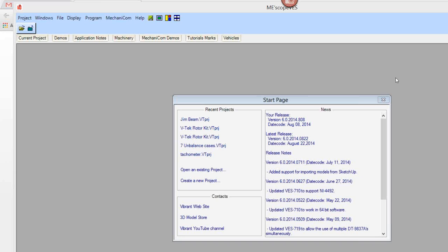But if we have an operating machine, or if we're testing a bridge or a building, something like that, we cannot measure the forces. The forces are distributed, they're internal, maybe they're acoustic, maybe they're the wind blowing on it, the traffic, whatever it is. We cannot measure the forces. So all we can do is measure response, and typically that's done with accelerometers. And then, in order to get mode shapes, or ODSs, operating deflection shapes, which is similar but different, we need a phase relationship between each of the responses.